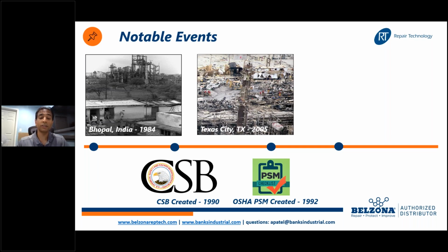But even still, in 2005, one of the biggest industrial accidents in the United States, the BP Texas City incident, where during the startup of a portion of a refinery in Texas City, there was a level indicator that was actually faulty. This level indicator because it was faulty, it allowed for the overfilling of a pressure vessel. A safety valve went off. So, okay, we prevented a pressure buildup and a potential hazard because of that.